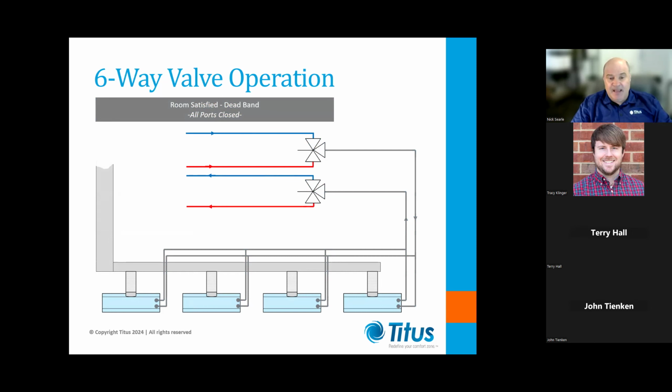but no cooling or heating from the beams is occurring. Now, if you've got a demand for heating, the valve will rotate from its halfway position and modulate up to full flow through the heating. So this can be modulating, or you could actually set the valve just to run in 3 positions: fully chilled water, fully closed, so deadband, or full hot water, 3 positions, or modulate. So either or. Anyway, so this is flowing the hot water through the chill beam. So now we're heating.